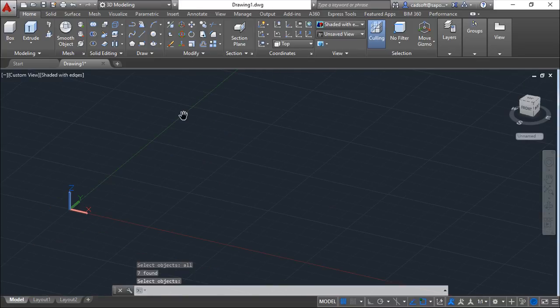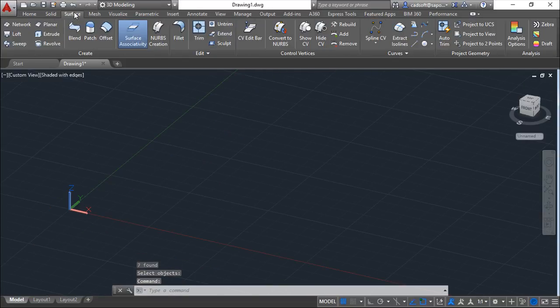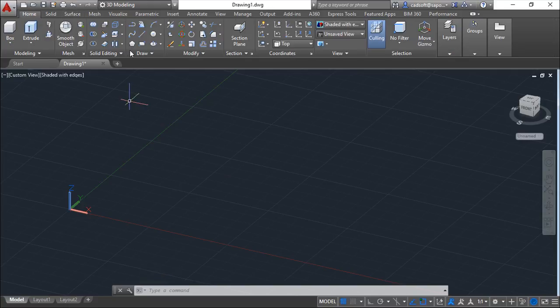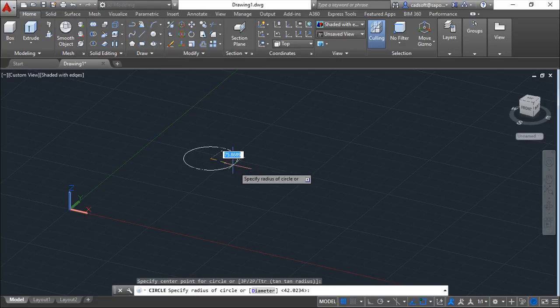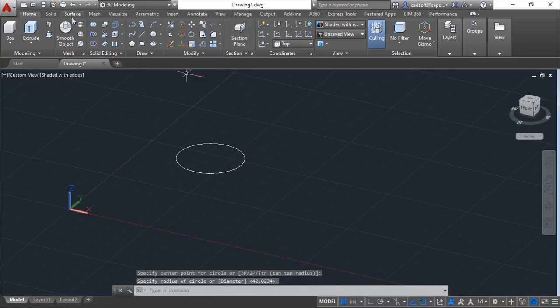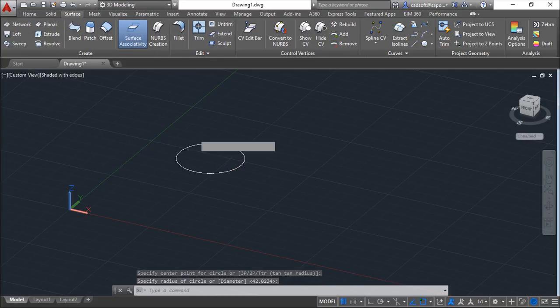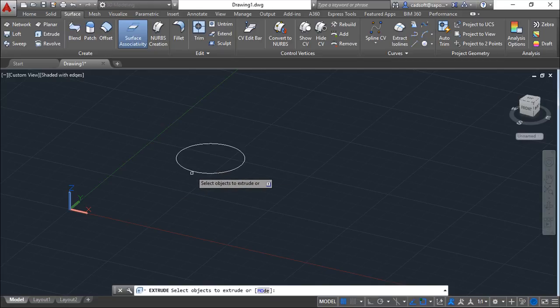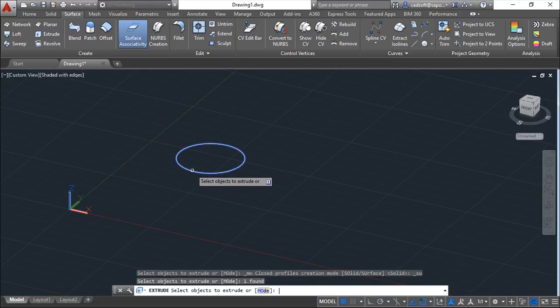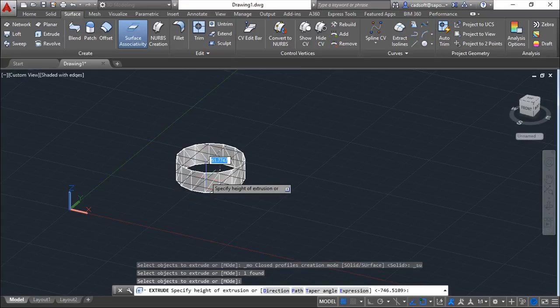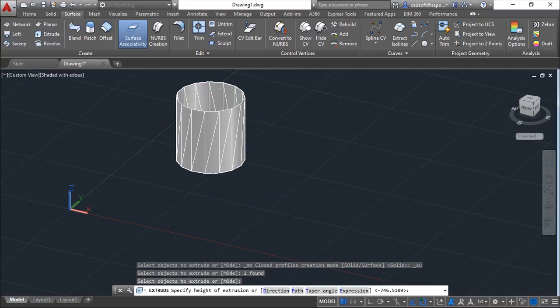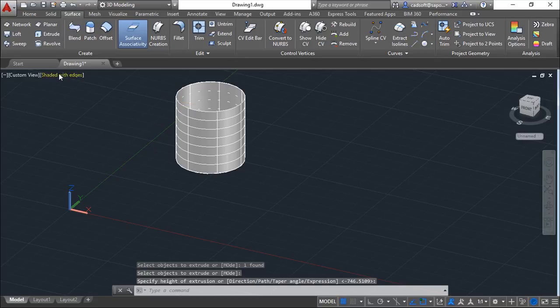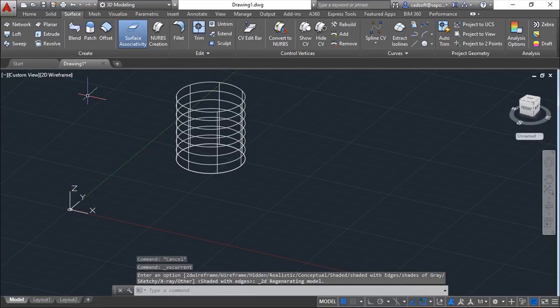It's the function called the Sculpt, this function here. So the Sculpt will allow you to have, let's create something first, a closed area and to apply like a super trim, and this super trim will cut everything and will create a solid from this trim.